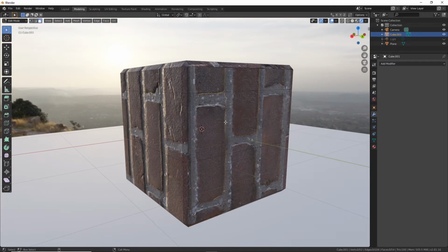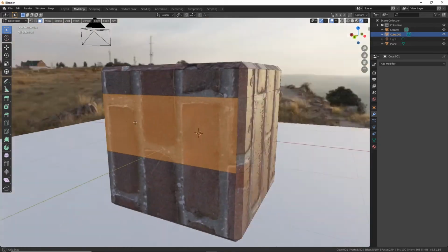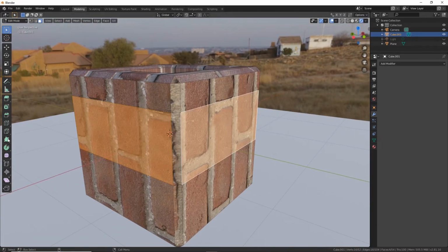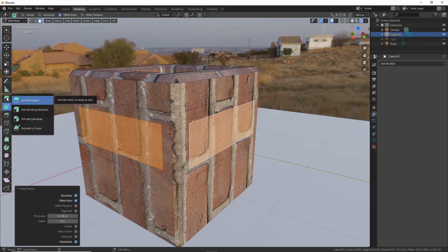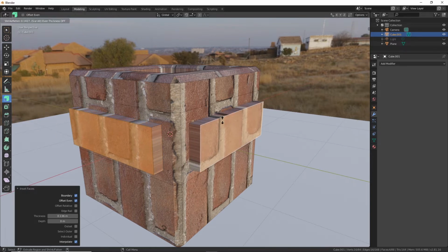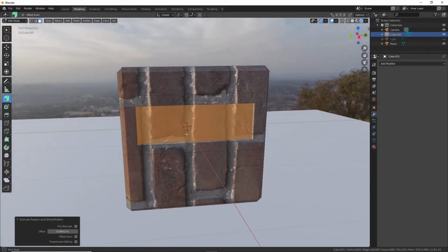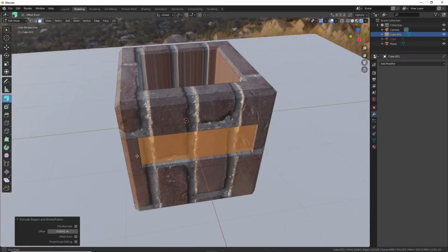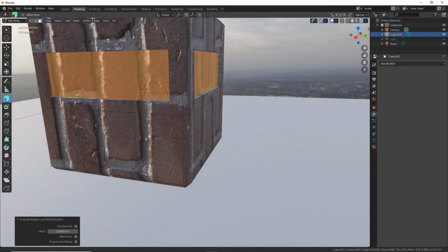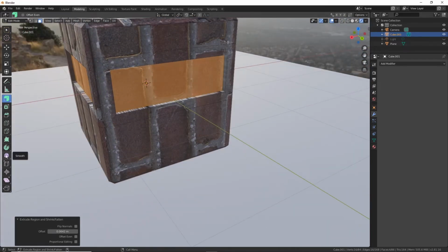So once I've added these edge loops, what can I do with those? I can select again by face and do some four-sided inset faces, and maybe then do an extrude along normals instead of the standard extrude regions. If I extrude along normals, it's basically going to extrude based on the face normal itself. So I can create some inset edges to this box that way. So anyway, this is just basic box modeling, me showing you some of these tools and how they work.